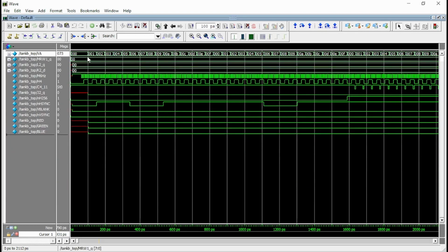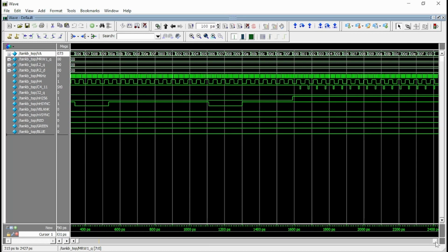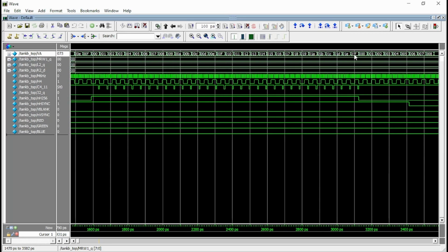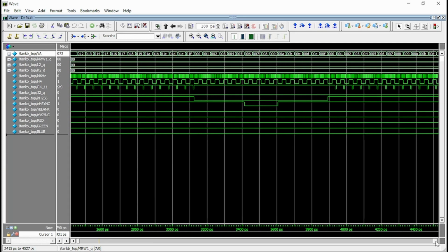And what it does is it creates a counter that goes from 000 to 00F, and then it counts again from 000 up to 1F. And then after that we come into our H blank, and during the H blank we're going to have our 0 to F again. And that was just a feature of how this counts.